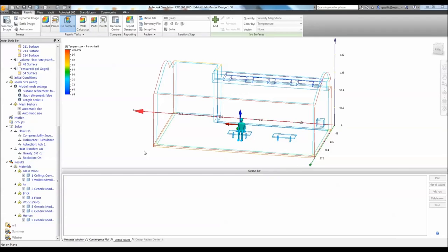So at the start of the presentation, we're focused on assessing comfort with the predicted mean vote. Thermal comfort, according to the standard, is the condition of mind that expresses satisfaction with the thermal environment. It is an important consideration in the design and layout of spaces. If you're doing building design or HVAC and air conditioning design, you need to understand what the comfort factors are in those areas occupied by people.